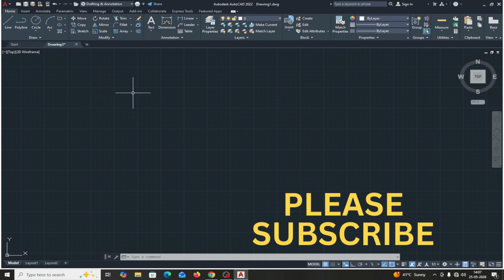First I will create two objects here. One is the line, with ortho on in the status bar, 1000, enter, out of the command. I am creating a circle here, 100 mm radius, 100, enter. These are the two objects.